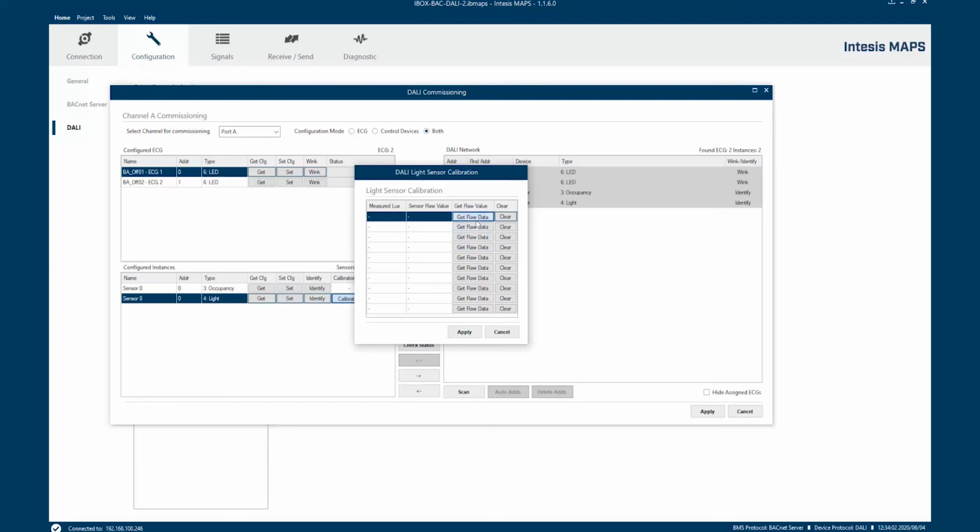So if I click on raw data, this is the information that my sensor is now measuring. Perhaps this information is fine, but if I measure on the desk surface with a lux meter, I find that the measurement is not 19, but with this light level it should be something like, for example, 10. Okay. I need to put more. The more measurements that I include, the more accurate the measurement will be.